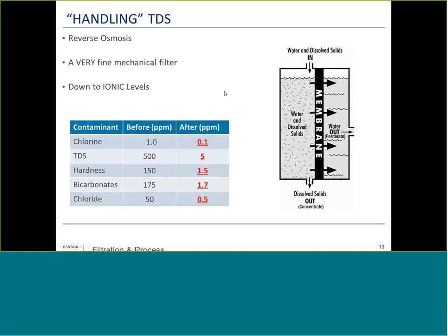And how reverse osmosis works, there's a restricted waistline that controls the reject rate of the water being forced in under pressure, which is then applied to the membrane. And essentially this membrane requires you to push the water through it because it's so tight it takes a driving force. And all that mineral content is left behind to flow out the waste tube.